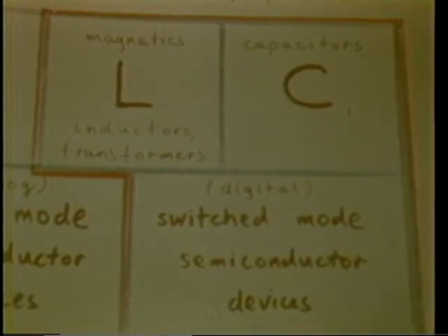So it turns out that right from the fundamental point of view, when you start designing power processing circuits, you have different pieces to put together into the jigsaw puzzle that's going to generate the final picture. And there's a basic conflict involved in that also of interest to the design engineers themselves: if you have to work solely with energy storage elements, the inductors and capacitors and switches, and you try to minimize the losses as much as possible because of the efficiency objective, then what you're going to get is very high resonances, very high Qs of tank circuits. It's sometimes difficult to accommodate those big resonances in the system design, but that's a conflict that exists, and it has to be recognized in the design of the system.